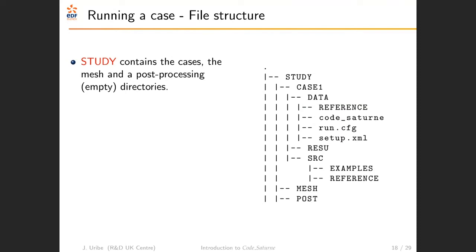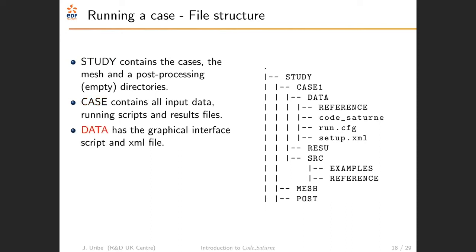When you create a study, you will see that you have a folder for each case, a mesh folder, and a post folder. Your case folder would be where you would put all the information for that particular case, and where everything will be stored after the simulation is completed.